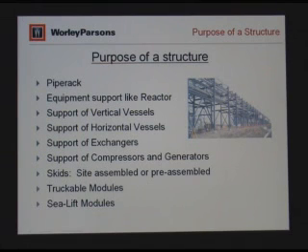For the other elements, we provide, of course, foundations for vertical vessels, horizontal vessels, exchangers, compressors. Compressors for us, in some cases, are interesting because we have to do some dynamic analysis, which for some of us is a deficiency, including myself. It's a really interesting design. We have to calculate the natural frequencies, make sure that there's not resonance between the frequencies of the structure, foundation system, and the operating speed of the machine, and also keep the vibration limits due to the unbalanced forces within tolerable limits.